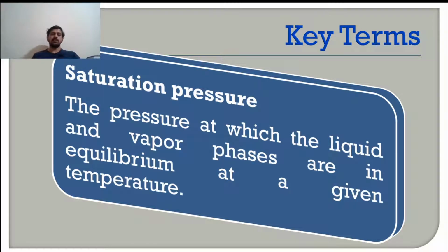So as we have discussed in the phase change process, saturation pressure and saturation temperature. We have seen what is saturated liquid and saturated vapor, as well as the saturated liquid line and saturated vapor line. Now saturation pressure is the pressure at which the liquid and vapor phases coexist. So you know that a saturation point could be there when the phase change happens from liquid to vapor, right? Saturated means that at that point the addition or removal of heat will convert one phase to another.